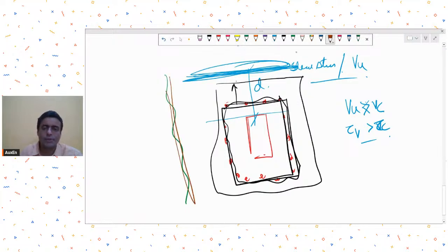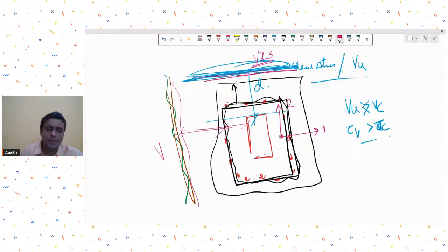So suppose you are getting confused whether it has to be added to one-way shear reinforcement, yes or no. You just check. Don't worry about one-way, two-way. Just check the shear values over here. So in SAFE, let's say this was local axis 1, this was local axis 2. On this line, you will be checking the V23 shear, and on this edge, you will be checking the V13 shear. Just check those shear values, see if that shear value is exceeding tau c or Vc. If it is exceeding, provide reinforcement. If it is not, don't do anything. Clear?